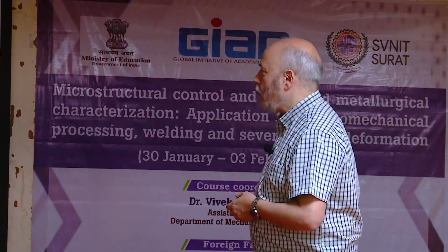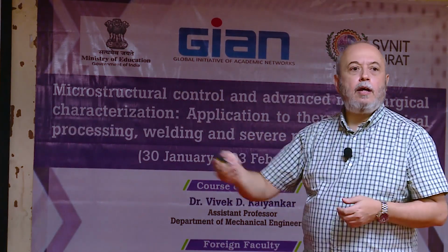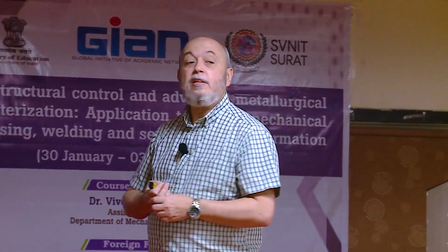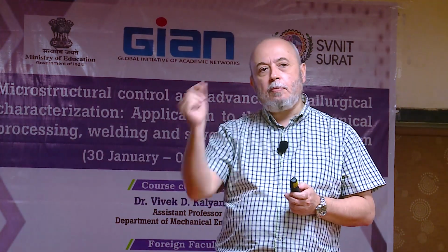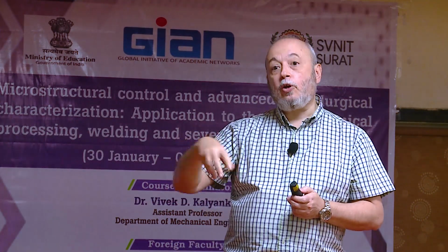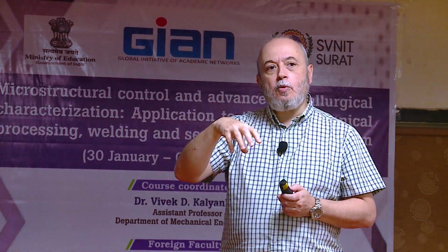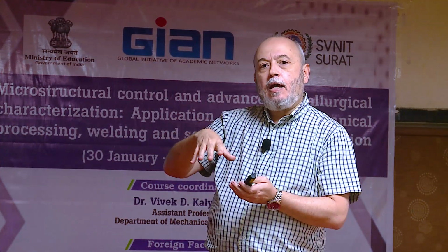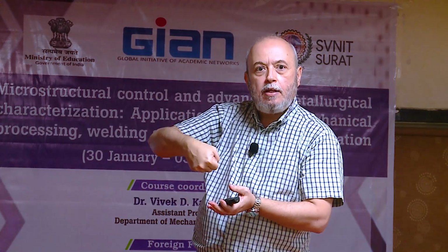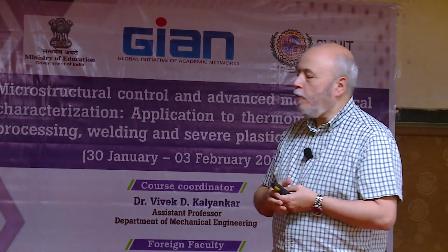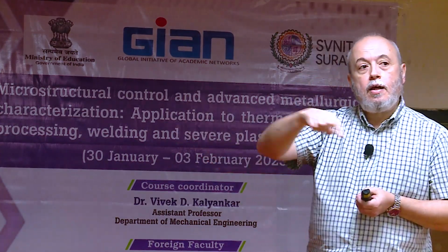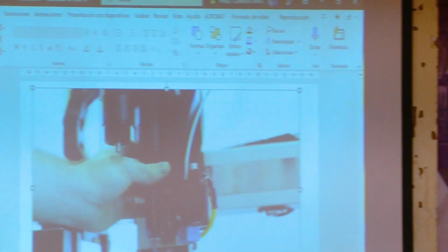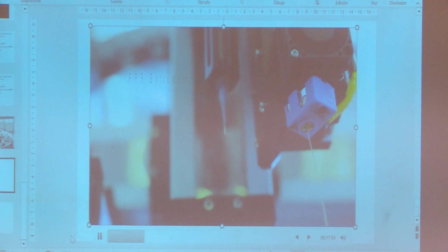For instance, and this is another video, we now manufacture direct ink writing printers. In these materials, we don't work with filament, but we work with pastes, or inks. We mix a polymer with metal or with a ceramic, and then we make a mixture, and then with a shearing we press, and then we distribute all the material, doing layer by layer, printing the different components. This is technology developed by us, and we sell these types of printers worldwide.